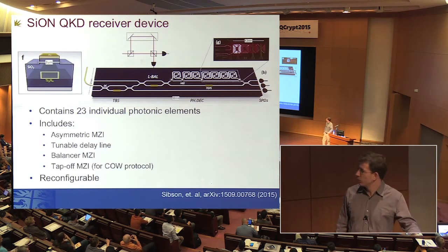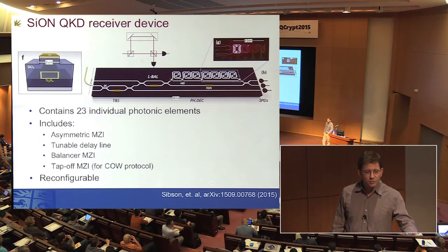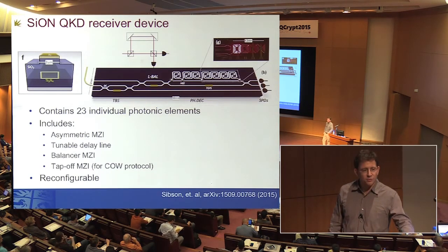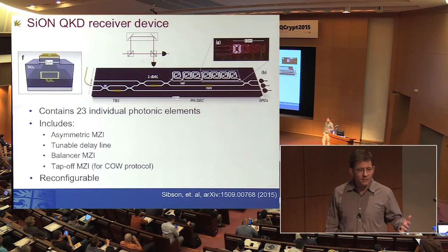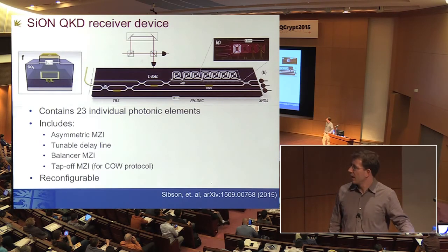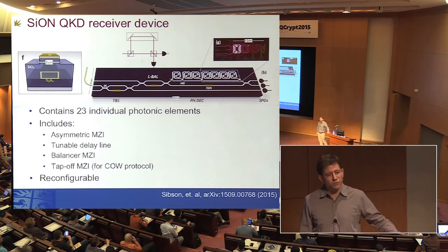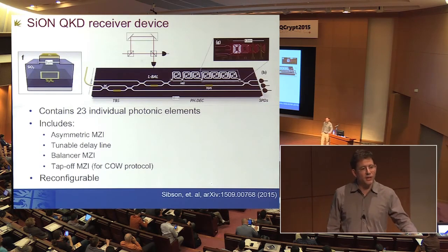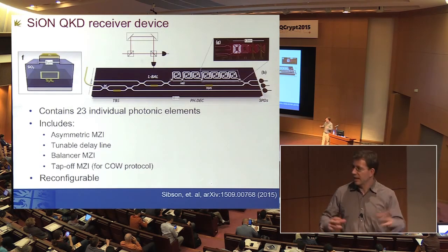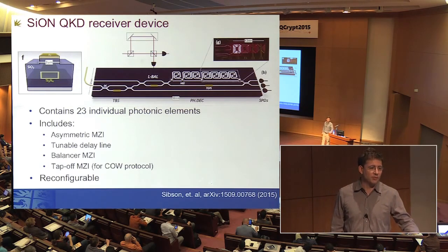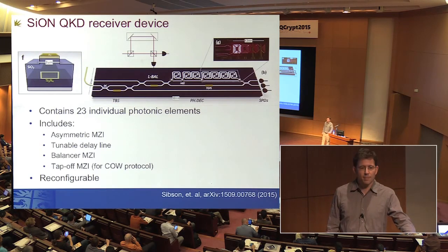To get around that, we do have ways. It's something called photon source multiplexing. What it requires is to integrate active fast feed-forward switching into these systems, but it's well understood. It's an idea that's been around since about 2001. We know how to do it, and that's what we're working towards, effectively an actively multiplexed, deterministic on-chip photon source. And once you have that, scaling up is not a problem in terms of the probabilistic nature of the sources.